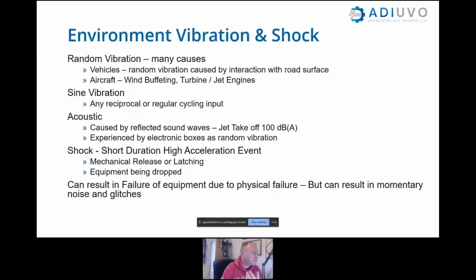We can actually see vibration and shock failures that cause issues in our FPGA. For instance, I've seen an FPGA locking up because bond wires were shorting as it was undergoing vibration. There was a one-hot state machine that had not been correctly designed, and it went into one of many illegal states, and therefore the only way to reset it was to power cycle.